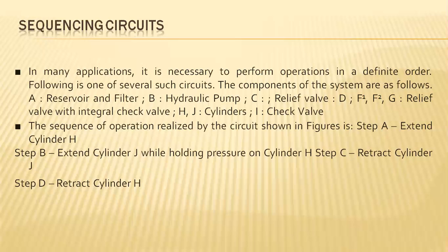And later on, instead of releasing the pressure, you are diverting the already existing pressurized fluid to another system directly or in parallel, indeed to perform both the actions in two different circuits simultaneously.